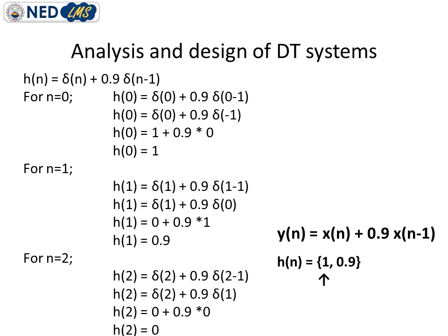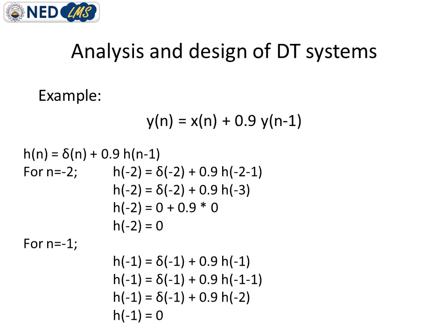So this is the question, which is again basically a difference equation, and we are going to calculate the impulse response from this equation. But before calculating the impulse response, we already know that this equation is for an IIR system, that is, the system which has infinite impulse response, because it involves feedback. And how is feedback involved? Because we can see in the expression, output is depending upon the previous output. So it means that some feedback is involved with this type of system.